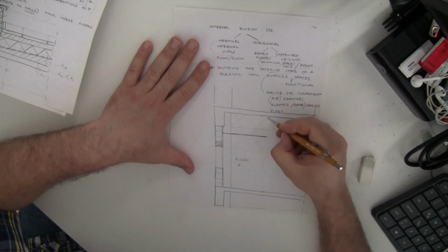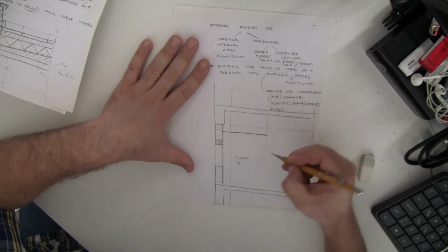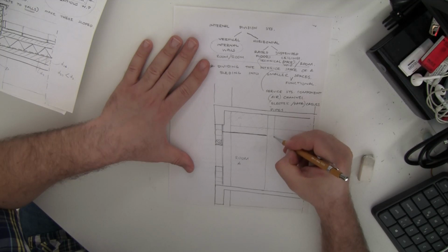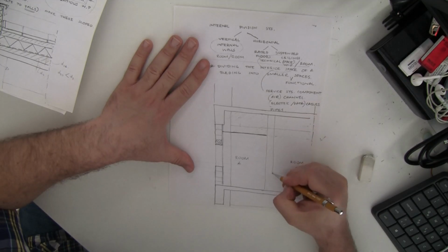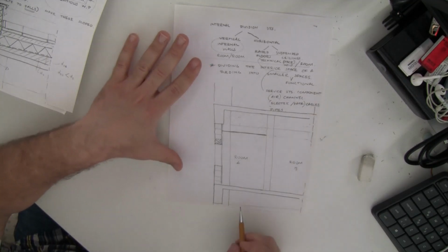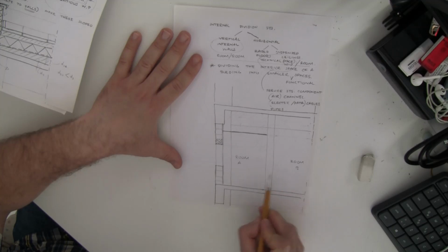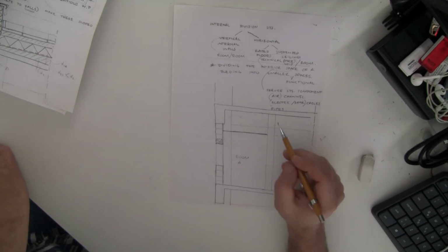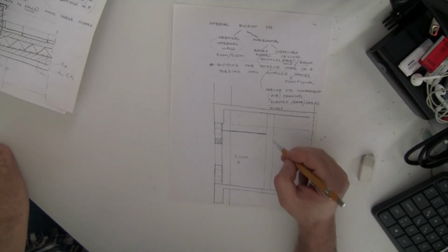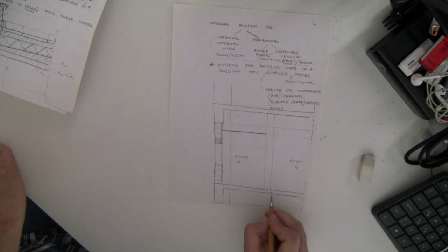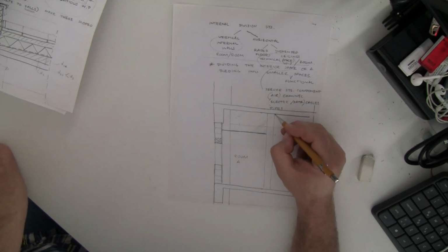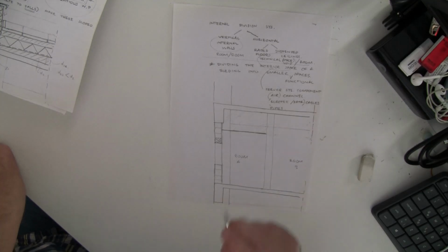So what will I do? I'm going to construct here a wall. Don't forget that walls will divide and separate these two spaces. So usually, 90% of the time, we want the wall to start from the top of the structural part of this floor and end below the structural part of the upper level.